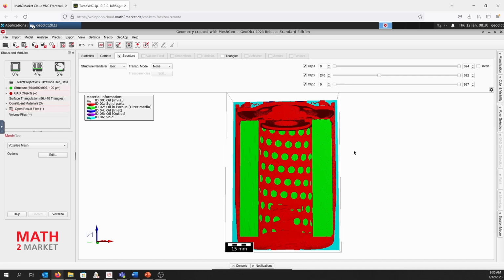So in general, this approach is here to check the influence without producing any pleated structures. For example, how would the pleat count influence the pressure drop, or how would an additional porous layer affect the pressure drop or other filtration relevant parameters.